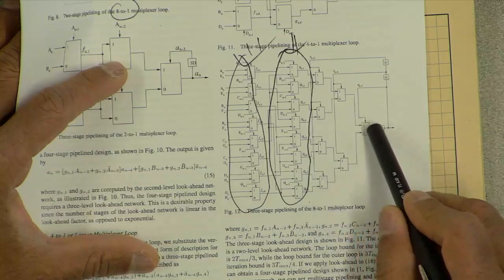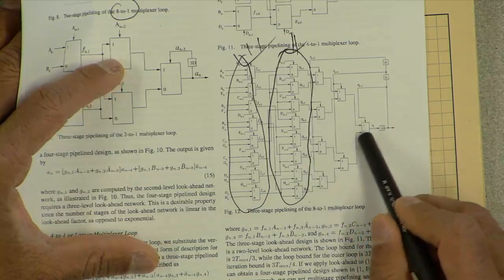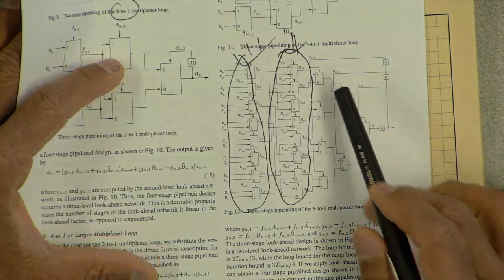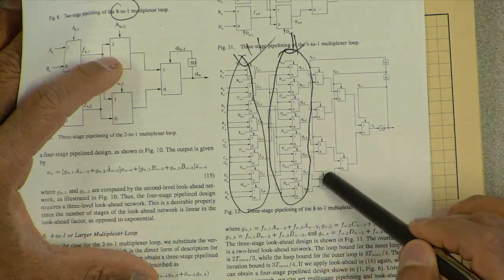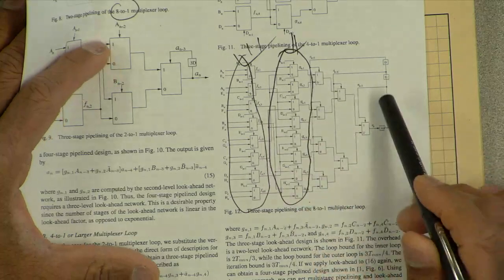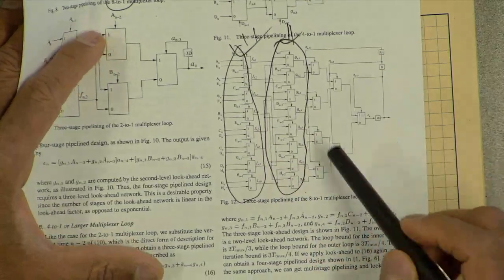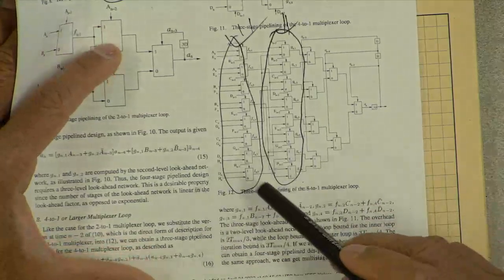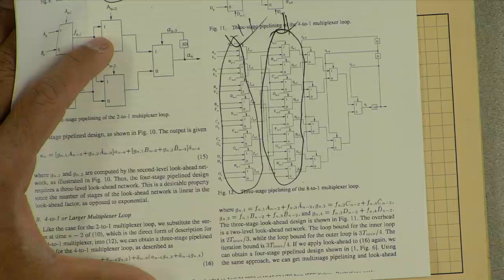These 3 delays are sitting lumped, doing nothing. Nothing is happening. But in order to get the true speed up, you have to unfold this by factor 3 and get a parallel structure that processes 3 input samples in 1 clock cycle. Okay, so that is one application.